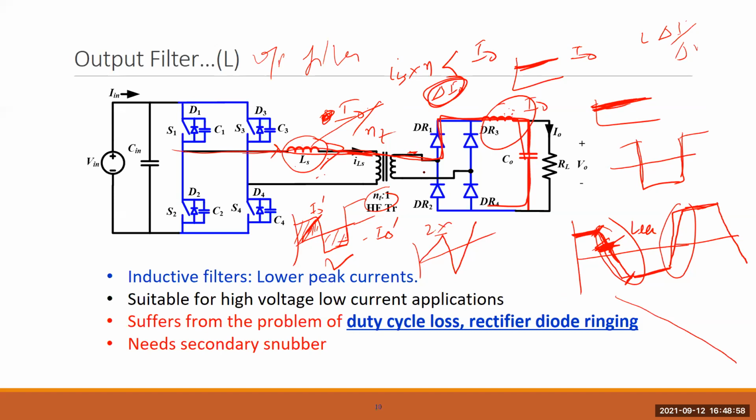Earlier this one was flowing through this, then this diode, and then coming back. So still the same thing is happening: the inductor current multiplied by the turns ratio will flow through this and come back. But the difference will flow through this pair now, because there is no other path. So the difference will flow through this diode pair on. It means all four diodes are on, causing a short circuit across the transformer secondary.